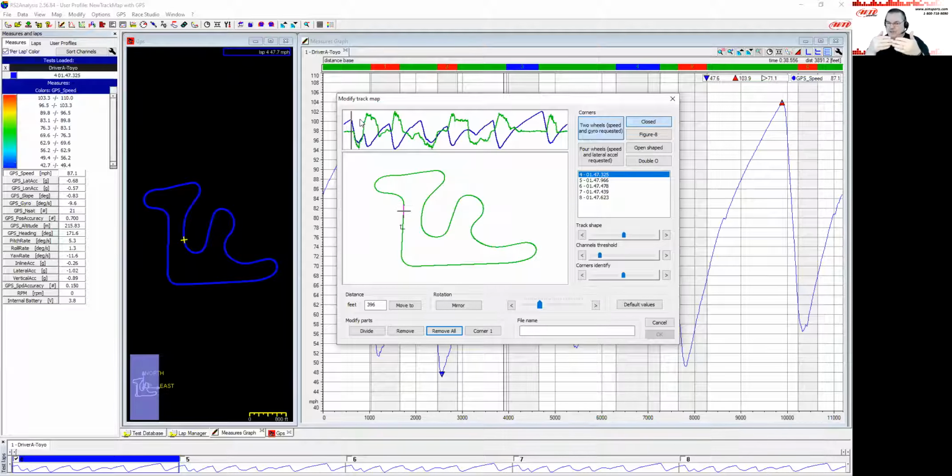The trouble is, if you put that split in our maps right at the spot where you do that transition, anytime you change your position where you do that, you're kind of tricking the segment reports, your theoretical best lap. All of these things become a little less accurate for you because the transition is right when you're transitioning out on the track. My suggestion to you is to look at that blue line up here, which is your speed trace, and right there is where you transition.